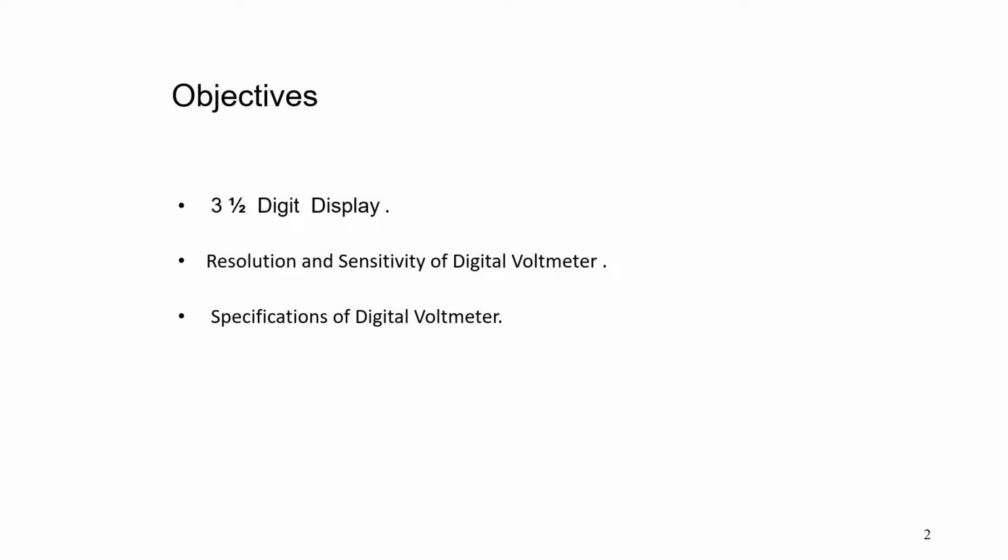The advantages of the ramp type DVM are that it is easy to design and its cost is low, though a single ramp requires excellent characteristics regarding linearity of the ramp and time measurement. But there are disadvantages with this ramp type DVM. Large errors are possible when noise is superimposed on the input signal. So input filters are required for reduction of the noise.